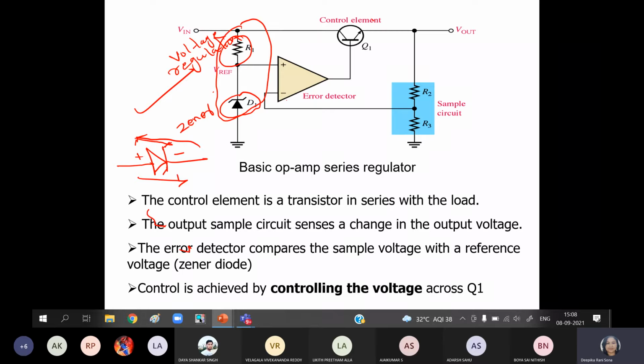Okay, this is up to this part, and that is connected. You can see that this part is connected to the positive terminal of the op amp, or we can say the non-inverting input terminal of the op amp, but it is connected to ground. So this is a stable, fixed part. We no need to do anything with that. We just have to check that, irrespective of the fluctuation in the voltage, it will give a stable voltage to the positive input terminal of the op amp.